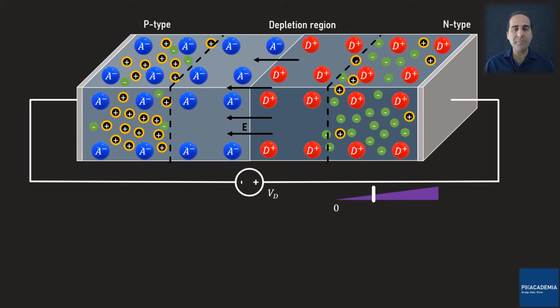Since under the reverse biasing the width of the depletion region increases, and therefore its electric field strength becomes more powerful, the diffusion process gets significantly weaker, and for a reverse voltage of a couple of kT, the diffusion current gets almost zero. As you already know, the diffusion current is due to the majority charge carrier concentrations. But what about the minority charge carriers? What happens to them? To answer this, I first focus on the P semiconductor.